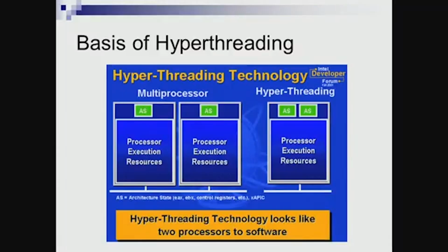In the case of the multiprocessor that you see on the left hand side, both processors will have both the floating point and the integer unit. So when one processor is executing the integer program, the floating point unit will be idle there, and on another processor, the integer unit will be idle. So in a sense we are not effectively or efficiently using the hardware given to us.